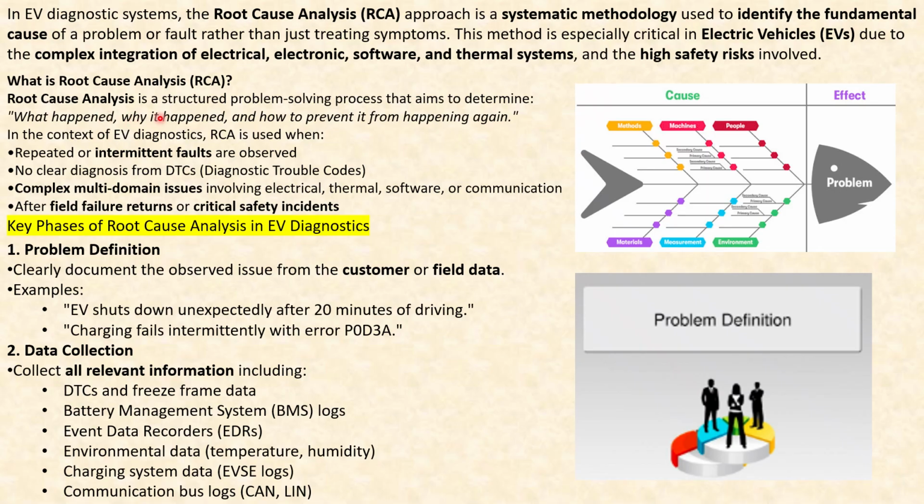Now, what is root cause analysis? It is a structured problem solving process that aims to determine what happened, why it happened, and how to prevent it from happening again. In the context of EV diagnostics, RCA, the root cause analysis, is used when repeated or intermittent faults are observed, when there are no clear diagnostics from DTCs, complex multi-domain issues involving electrical, thermal, software or communication, and after field failure returns or critical safety incidents.